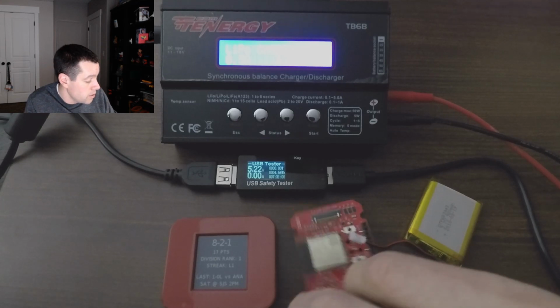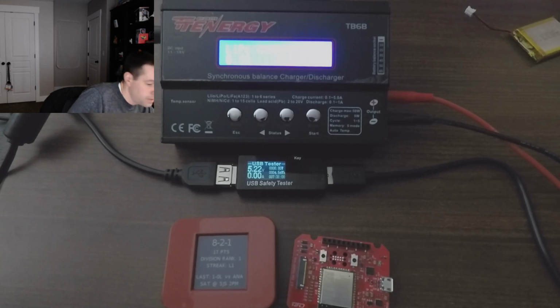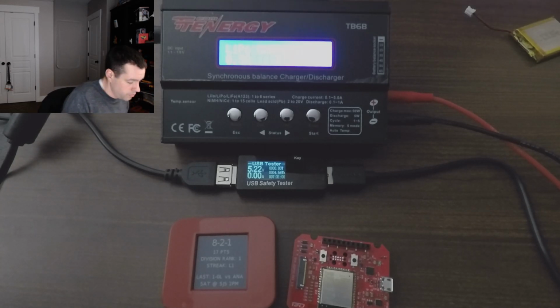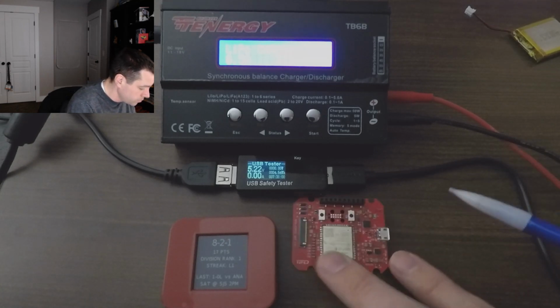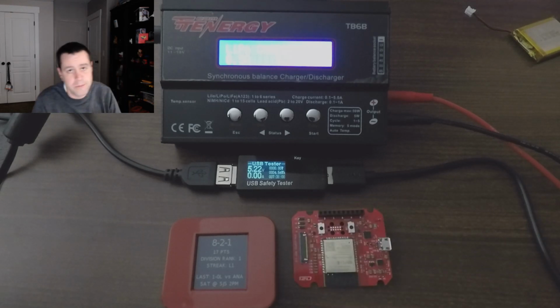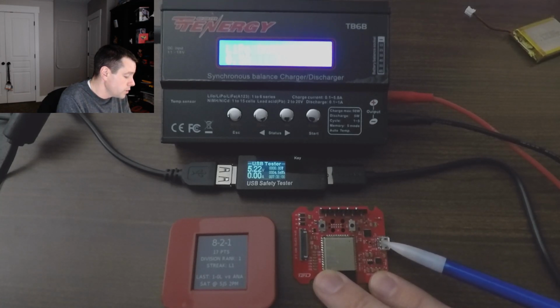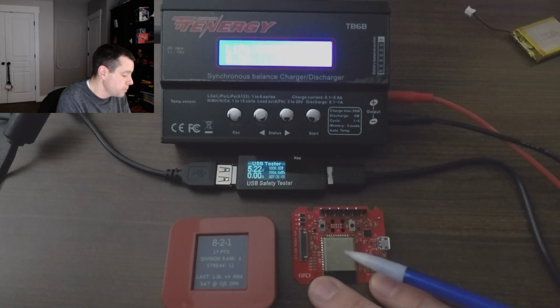And in fact, let me get a pointer here. Okay, so right here, this chip right here, this little black square, that is the FT230XQ? What is it? I think that's right. It's an FTDI chip that does USB to TTL. So this chip right here takes input from the USB and turns it into just serial ones and zeros to go to the ESP32.